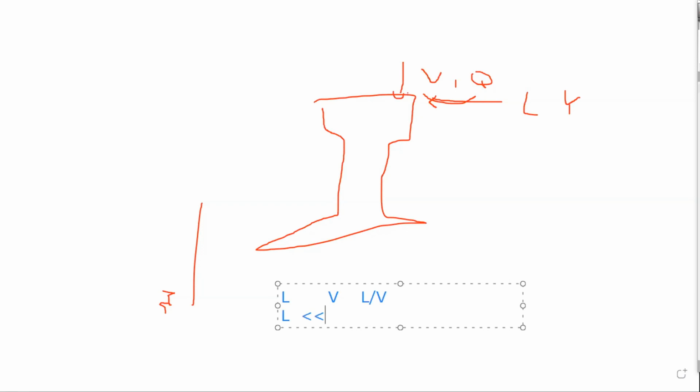V is a funny animal. V can't be too high and can't be too low. If V is too high, for example, greater than 400 kilonewtons, or greater than 300 kilonewtons, it's going to break things. You're going to break your rail, you're going to break your wheel, you're going to damage your track, you're going to crack your sleepers. So you can't have V too high. You can't have V too low also, because if V is too low, then there's nothing holding your wheel down on your rail. And there's nothing keeping that wheel from bouncing up too much and then derailing.